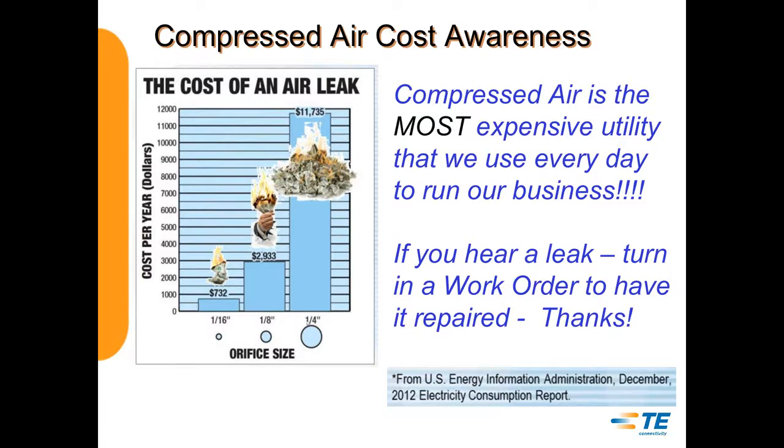One of the things that most people don't know, that I've recently learned, is that for the amount of energy that you put into a compressor to compress air, about 70 to 80% of that energy leaves the compressor as heat. So when you go into a compressor room, there's usually a lot of airflow. They're usually fairly warm, especially during the summer. But that's where most of that energy goes, into generating heat when you're making that compression. So right off the bat, without any leaks, compressed air is already like 4 times more expensive than electricity because of that loss of heat during the compressing process.